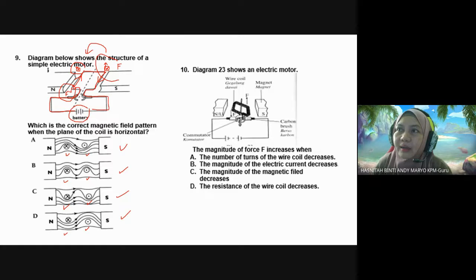It moved downward on the left. It means that which magnetic field is stronger, on top or below, students? On the left side. Since it is moved downward, it means it has a stronger magnetic field upwards. So this is correct. Okay, this one also correct. These two are wrong. Because if they show this drawing, mean this conductor will move upward. So C and D is wrong.